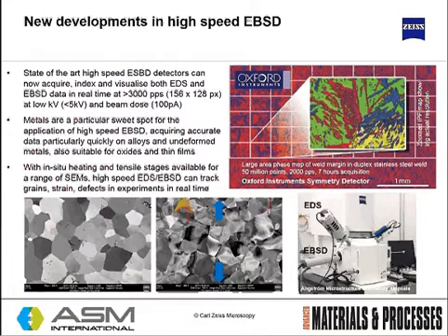So the latest thing in high-speed EBSD, and I'd like to thank Oxford Instruments for these images and data. The new Symmetry detector, for example, is able to do this. The sample here, top right, is a duplex stainless steel. You can see the blue is ferrite and the red austenite in a weld. This image was collected with roughly 50 million points at 2,000 points per second, so that's roughly 7 hours for this. As you can see, it's a several millimeter cubed sample. To zoom in, you can see the true resolution of the map and the actual resolution.